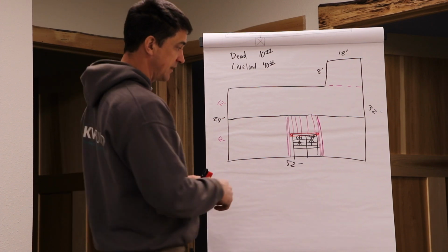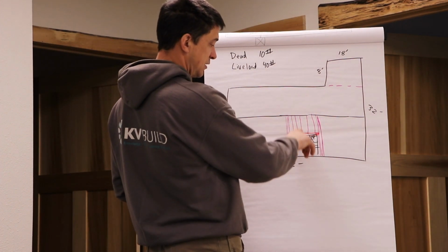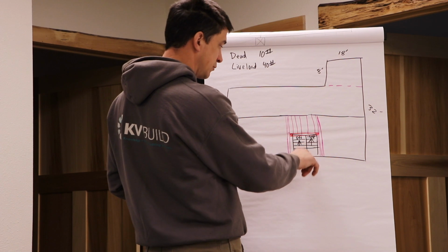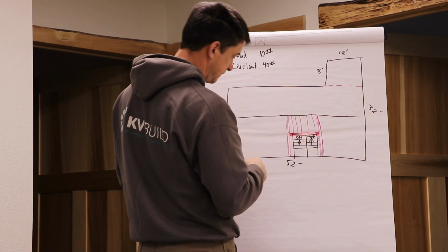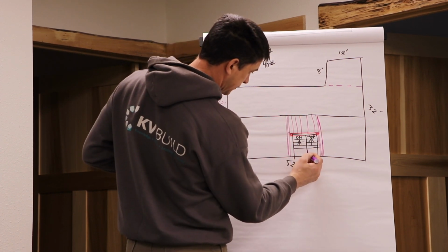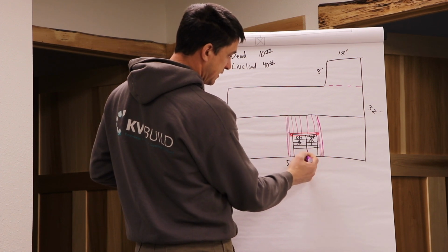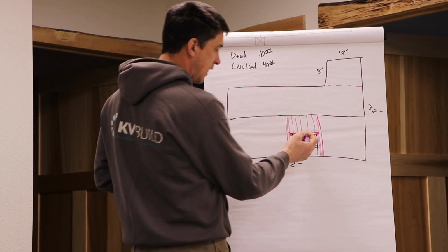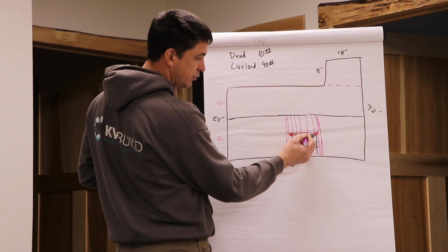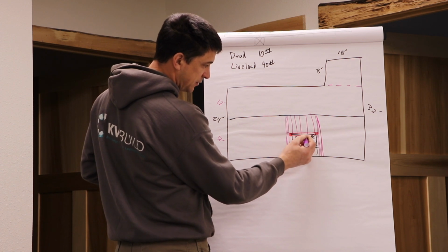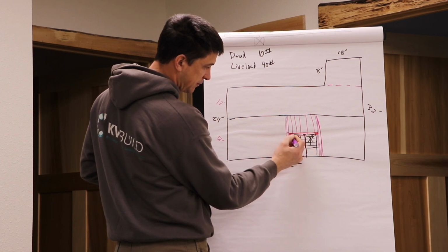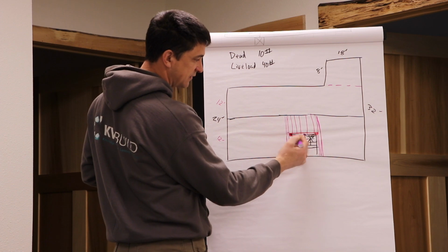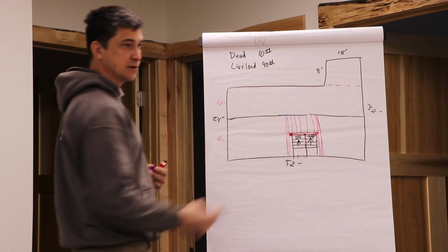If they don't care about how this looks down here, you could build a wall in between. This line shouldn't be here. Because this is a landing, the entry door is there. So maybe we can build a wall here and have a load bearing point there, and a load bearing point there, and we just have to have a header to carry these 2 floor joists.